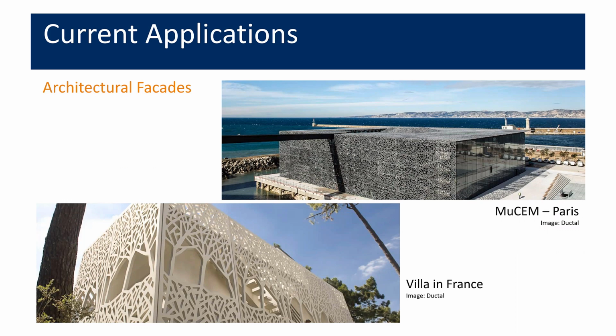So you can use thinner, lighter weight elements. Because it's self-consolidating, it can also fill more complicated forms. So you can get more intricate forms and more intricate patterns like I'm showing here in these particular architectural facades. It can also be produced with white cement, so it can be white or colored to suit certain projects' aesthetic needs.